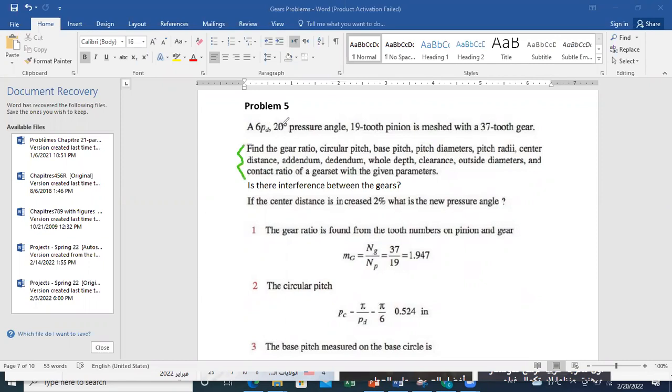So first, we know the diametral pitch. Here they call it PD, in the course we call it DP. So it's equivalent, whenever you have P and D, this is diametral pitch. And whenever you want to talk about the pitch diameter, you can just put it as D. Okay. Now, this is the number of teeth.